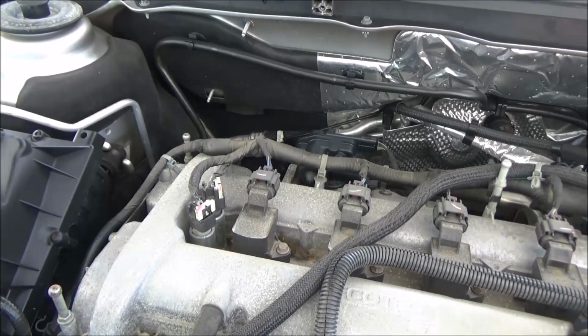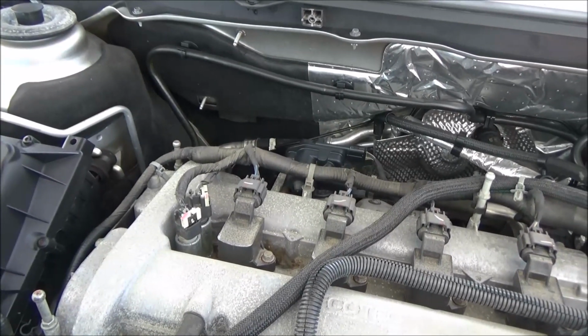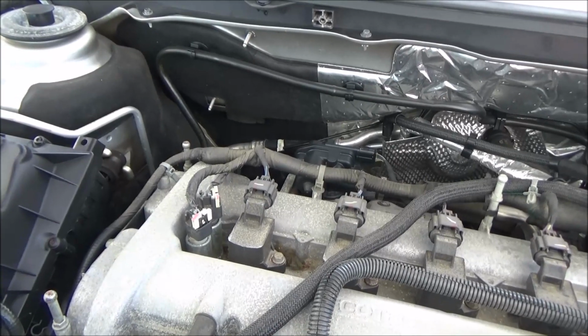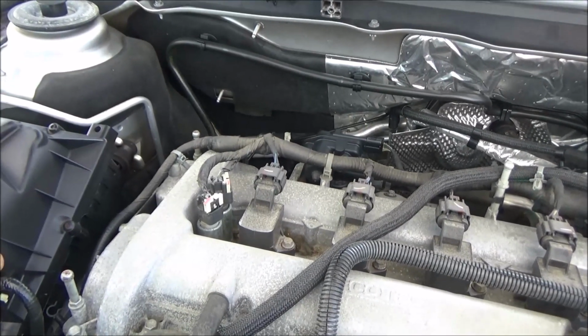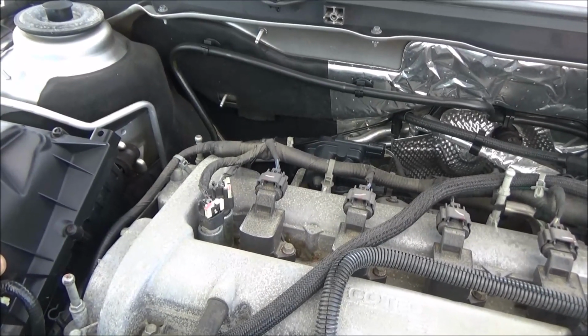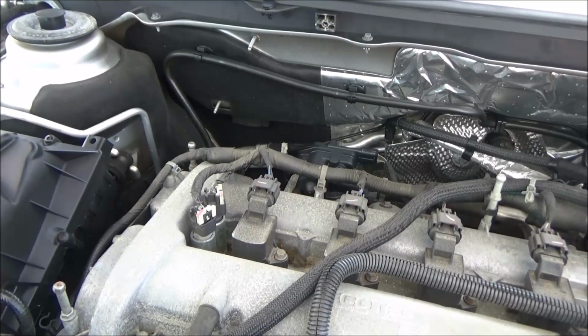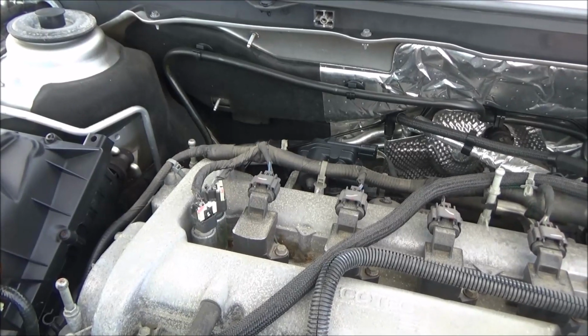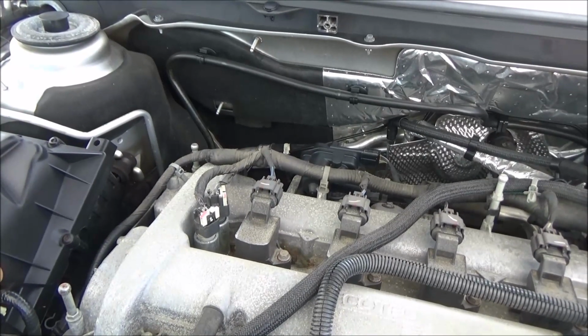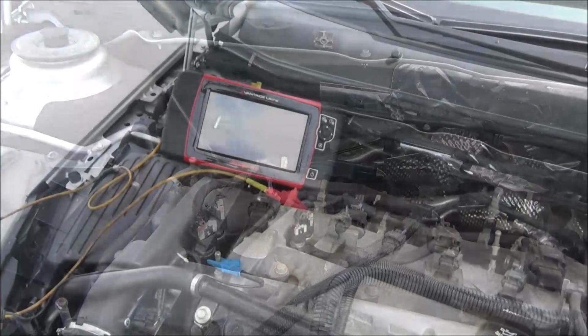We can do a couple of other things. One thing I will mention is I've had great success in the past using an ohm meter to test these. Generally what I see resistance wise is 10 to 13 ohms. But just to get a better feel for how this system works, I think what we're going to do first is we're going to actually use a lab scope, and we're going to check these solenoids. So that's coming up next.